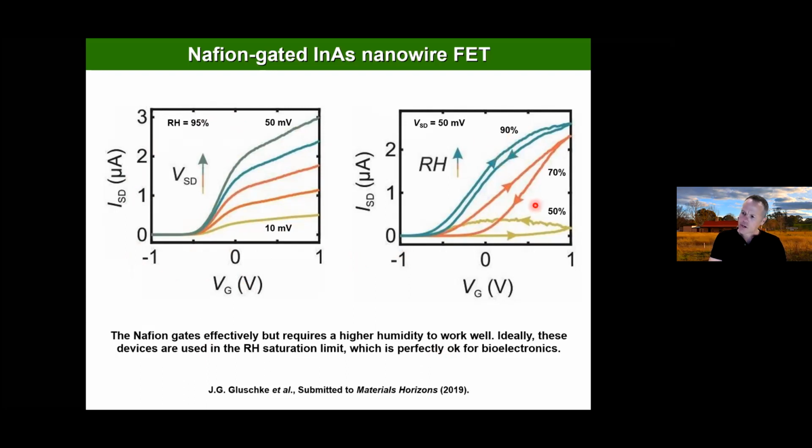And the hydration for these is very, very important. If you don't have a lot of water in that Nafion film, it doesn't gate very well. But that's okay for sort of bioelectronics applications because you're usually going to be in wet environments anyway.